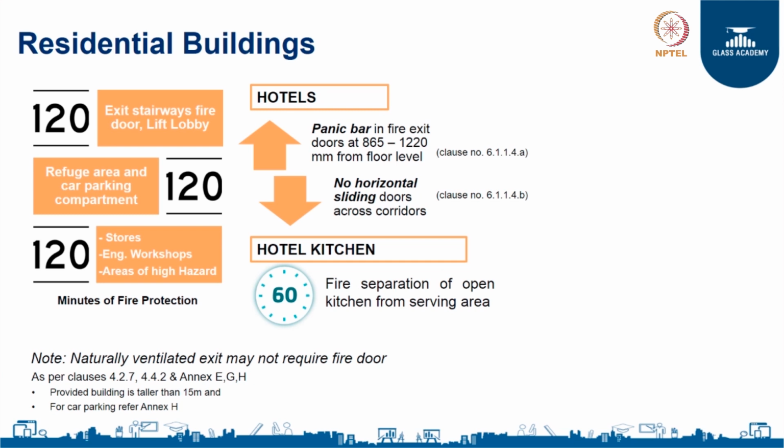And also in hotel kitchens, nowadays you see a lot of open kitchens and live kitchen counters. The regulations are such that one needs to use a 60-minute fire rated glass in such applications. So, the next time you visit a live kitchen counter where you see chefs preparing a dish right behind a glass, please check if it is a 1 hour fire rated glass, because as per the regulation it has to be a 1 hour fire rated system that has to be in place.